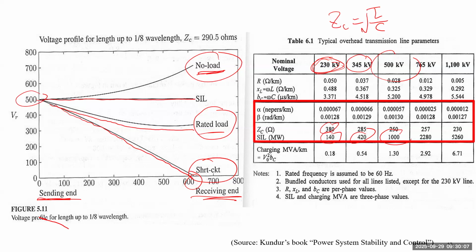But usually when we define the voltage level, we don't just check the nominal load. There are many other considerations. So when you operate at very high voltage, for some conditions you don't have to power this much load. You may only power a load much less than this value. So for a high voltage line, you are more likely to see some overvoltage issues if your load is lower than the surge impedance load.